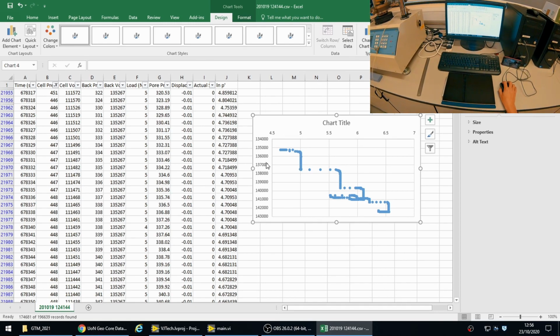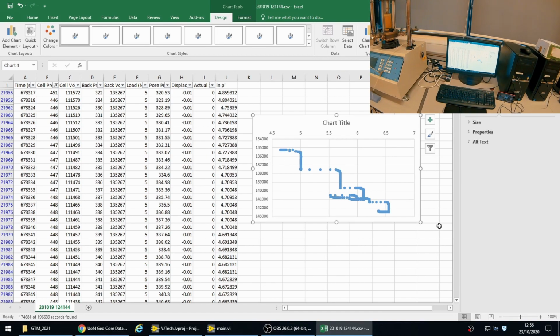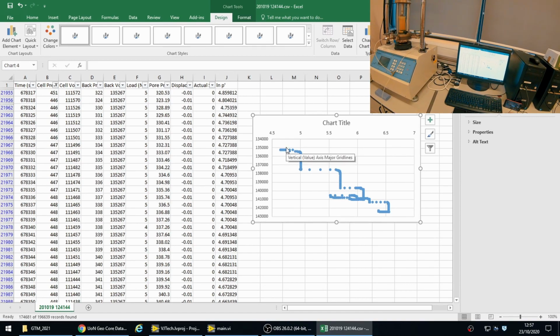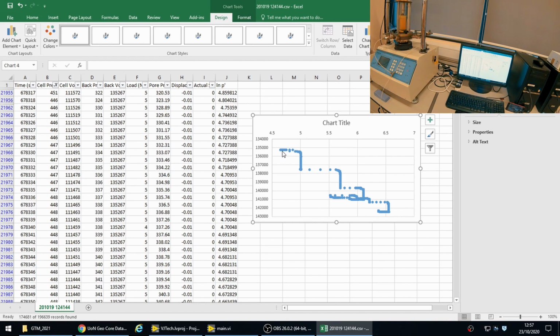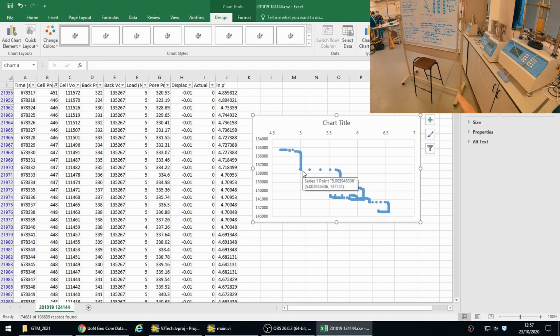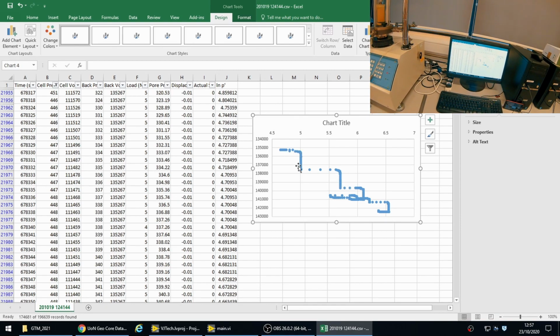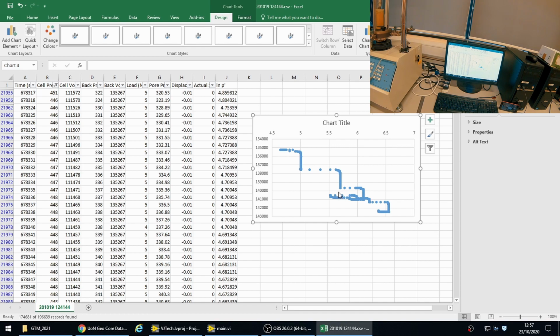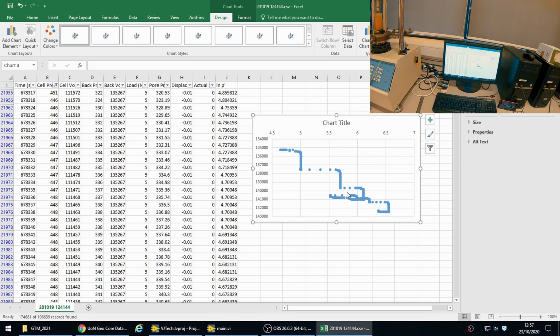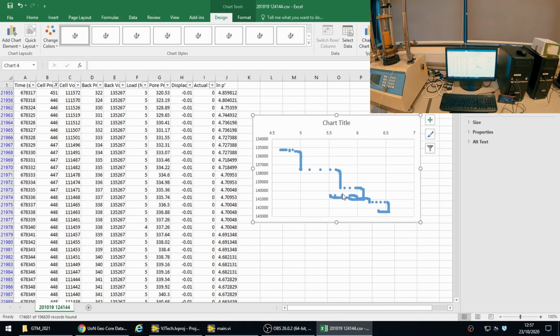You could plot them using a graph like this, if you were to do a bit more processing on the data, get the specific volume right, and plot the specific points for the specific p dash at close to t100 for each of these lines. Obviously this is showing you the consolidation behavior over each successive increase or decrease in stress, but that looks broadly similar.